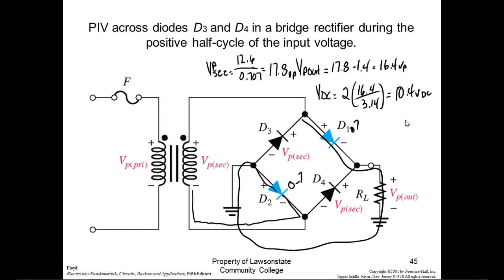But another feature is that the polarity is determined by how we connect the load to the bridge. So I can use one bridge and they're there side by side, and one of them gives me a negative power supply, the other one gives me a positive power supply. But I'm going to show y'all something in a minute that's very popular.